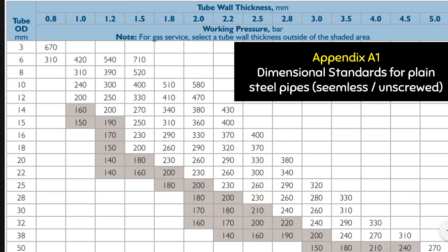In addition to this, you'll also find other information online from the manufacturer or the supplier of the piping. So if you don't see this, move along to another supplier. You should always make sure that you have this information available to you. If not, don't trust the pipe, don't use the pipe, get another pipe. Usually the diameters of the pipe will come with available ranges of wall thicknesses. And also each pipe's respective maximum working pressure or temperature will be given to you, specifically pressure.